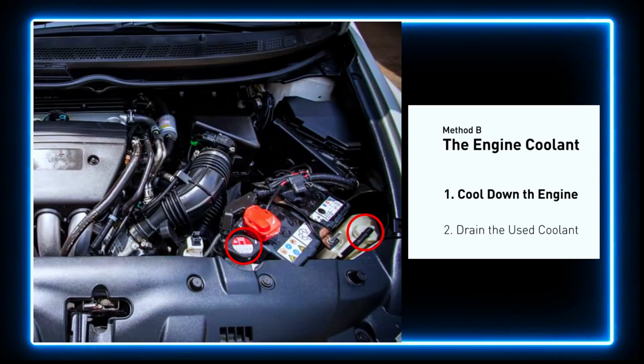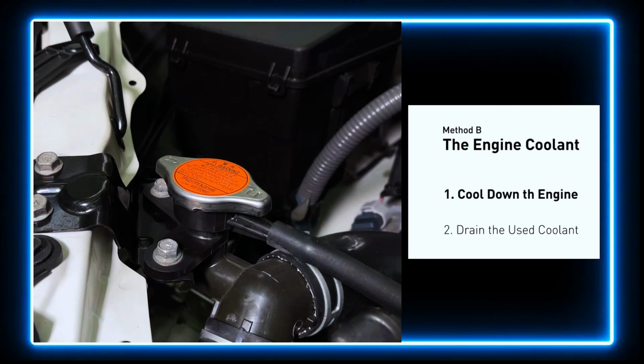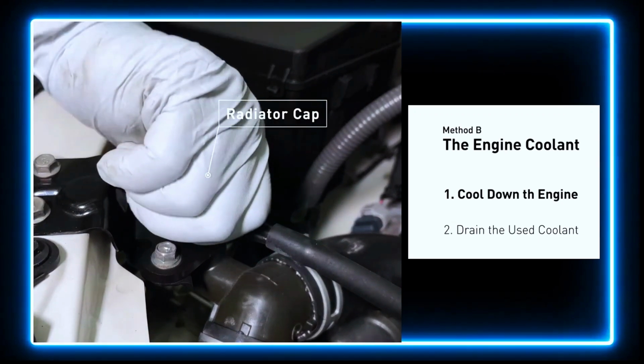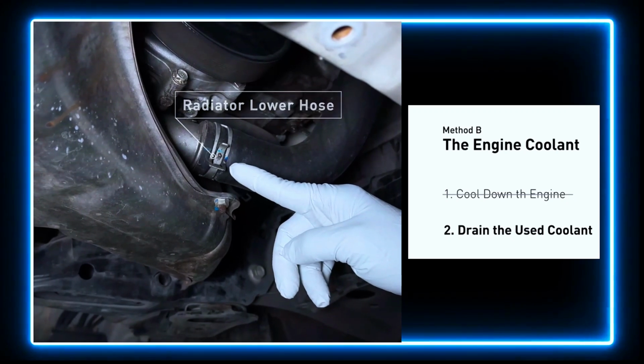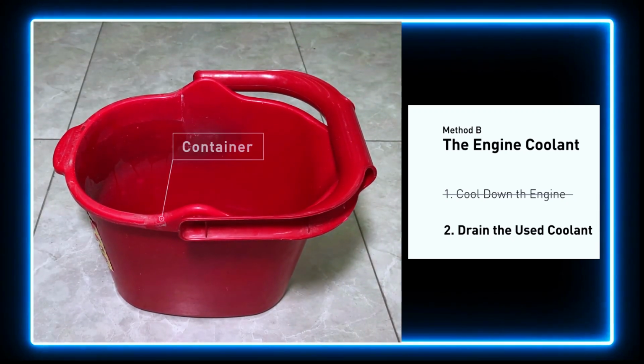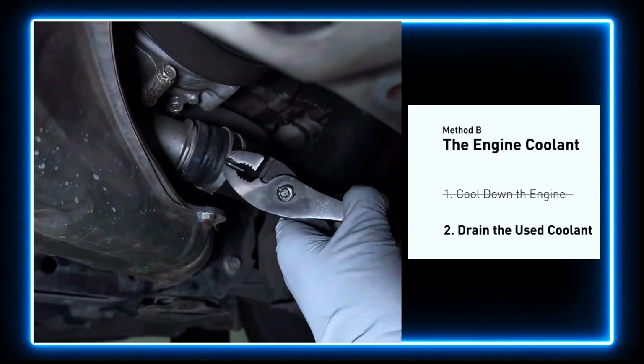The engine coolant reservoir is often a translucent white bottle, and the radiator is the large panel at the front of the car. Cool down the engine and remove the radiator cap. Locate the radiator lower hose. Place a container underneath the hose. Remove the hose and allow the coolant to drain.